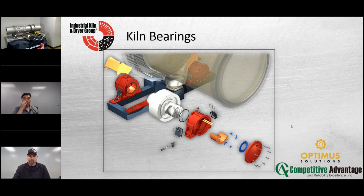You'll see this orange here. That's the kiln sleeve, the bearing sleeve. You want to make sure that there's nothing there, because if you get a groove, and this is important to talk about, if you get contamination, there's grooves, you actually reduce the viscosity of that lubrication, because you actually, in a sense, puncture it. And we can go through, if you guys got more questions on that, we can talk about that later. It's like you put water on a penny, how it kind of bubbles up. If you put a slice in it, it divvies it and actually breaks that bubble. If you touch it, it breaks it. That's the idea here, is that you can actually screw with the lubrication because of the grooves in there.